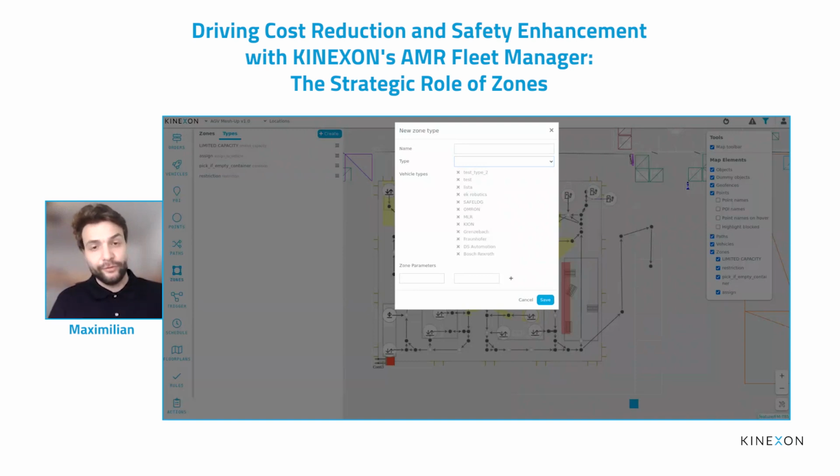precision and speed is often difficult to unite together. So in free drive on a free area, they usually have a higher tolerance than if they're trying to find position under a load carrier. If you have 5 to 10 centimeters, you're driving 2 meters per second. This is quite useful, that you have a camera that already warns you a little bit earlier than your safety fields come in, so it slowly brakes down instead of going into a safety field violation.